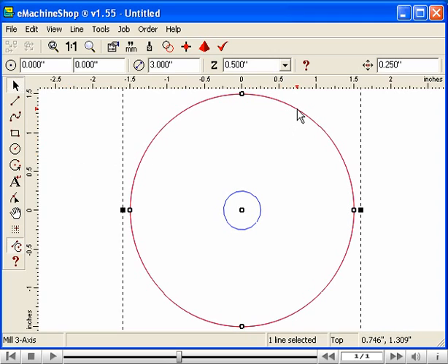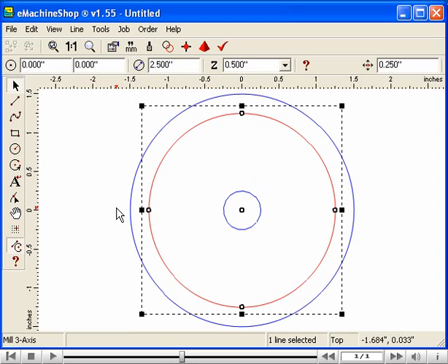Now set the diameter to, say, 2½ inches. Notice that the size of the circle has changed. Now make this line a recess. Set Z to -0.2 to indicate that the material is recessed by 0.2 inches. Negative values make recesses. Positive values make protrusions.